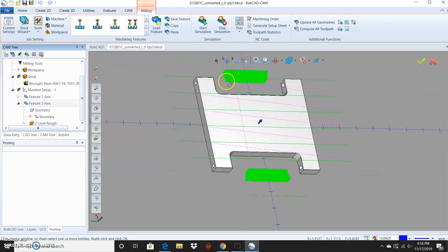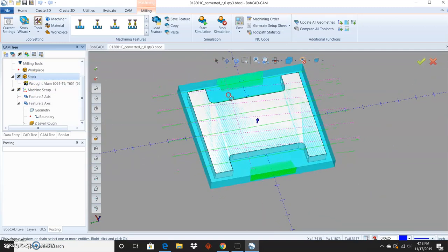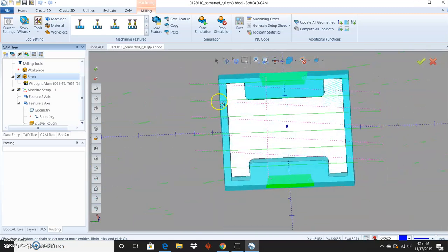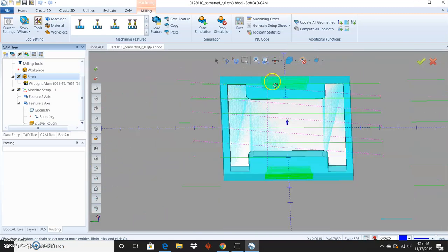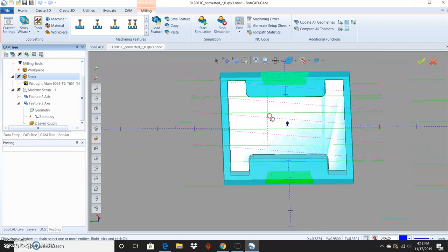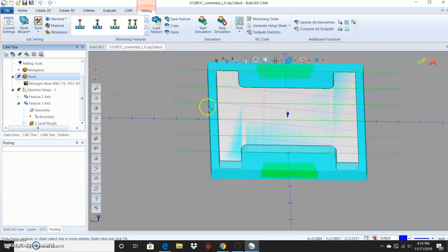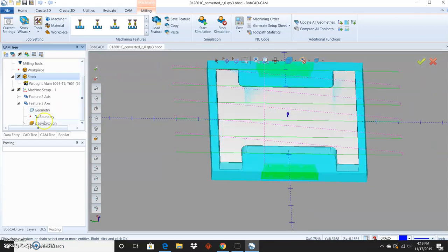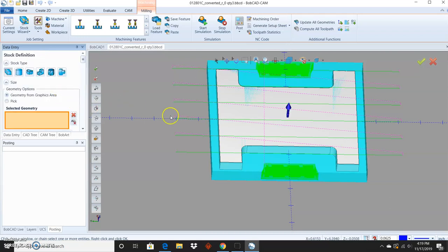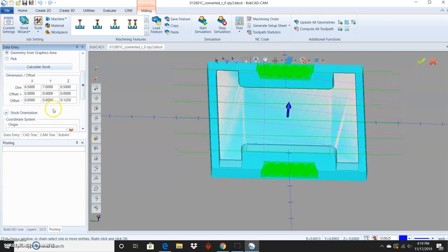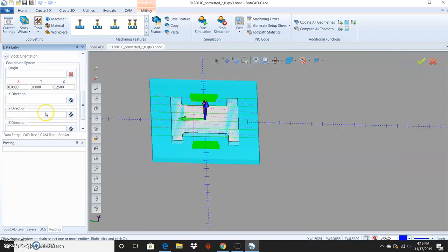So because of the size of the tool and where my stock is at, with that big a tool, it's only thinking it can fit that tool within that stock. So if I want to use that tool with a 3D path, I have to lie to it and tell it that my stock's even bigger than that. Or I have to use some sort of 2D method that isn't stock aware. So just come here and make my X 10, 10, and we'll say okay.